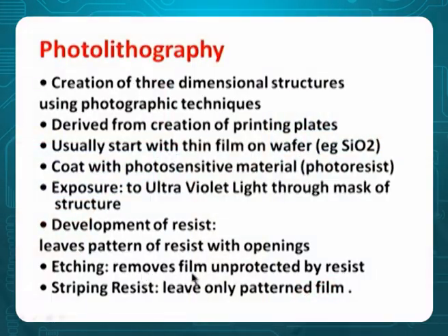So photolithography is removing whatever unnecessary portion is required. Etching, removing film unprotected by resist. Stripping the resist, leaving only the patterned film. So this is all about photolithography, what we do in IC fabrication.